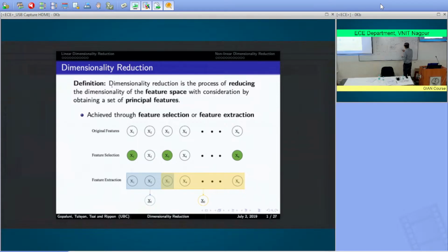in process monitoring. Okay, so you have, let's say, a couple of variables, x1 and x2. They need not be the true variables. They are probably variables in the reduced dimensions. So you have, let's say, 5 different variables. You reduce the dimensions, get them into 2 different variables. You can plot these variables in 2 dimensions and observe your process. If there is something that breaks down with your process, the underlying system dynamics, then you will notice that these data points move to a different location in the lower dimensional plot. Okay, so that tells you maybe something has gone wrong with your process.